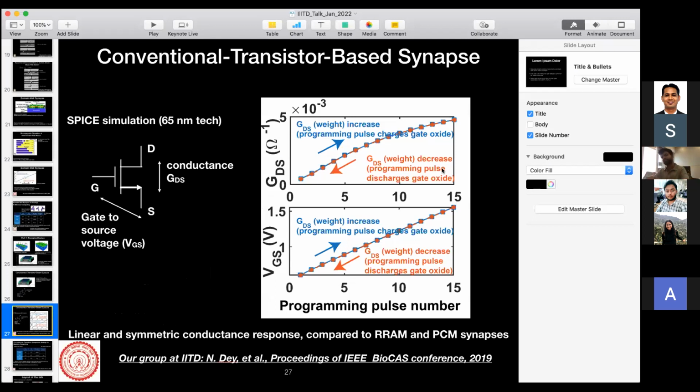If it starts losing that value, I cannot really feed it current and bring it to the particular value I want. You get what I'm saying? If it was just storing 1 bit and it was losing it, you can put a current. In DRAM, I don't think you have a controlled current, right? You just refresh it by putting the same amount of current, and it just stores it. So a DRAM idea will work. Instead of having one synapse, if you have 5 or 6 transistors, and I'm refreshing each of them, then this will work.